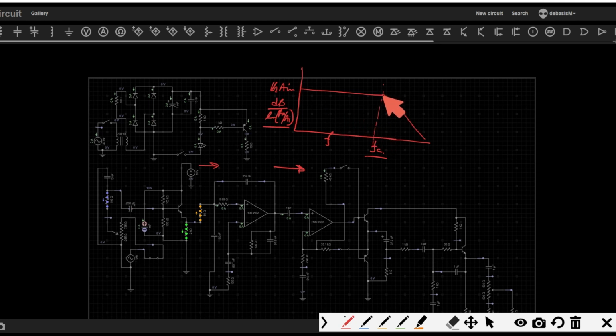Okay, so whatever is before this critical frequency is retained, it may be boosted also. So there are scenarios, but just keep it simple. So here the gain is 1, so it will allow the signal to pass till this fc. But beyond fc, as the frequency of the signal increases, it will reduce that gain. Means if here you have a large amount of very high frequency, like intense guitar sound or some hissing noise sound kind of thing, those things will be grounded, and here we will be getting crystal clear sound with the frequency of this zone only, maybe some amount of here also.